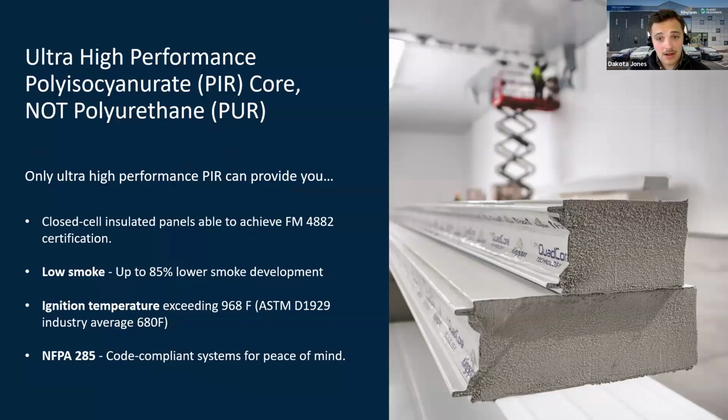But standard PIR, which is shorthand for polyisocyanurate, is kind of an industry standard now. And the reason for that is our R-value, on average, is like 7.2 per inch, which is great. But mainly it's for fire performance. Plastic insulations have gotten a bad rap. A little bit before us, as an industry, we used to use polyurethane insulation. And this stuff, if you know, was horrible as far as fire performance is concerned. It smoked quite a bit. It dripped, it bubbled, it just wasn't safe to be around. And its R-value was like 5.2. It wasn't even worth keeping around.